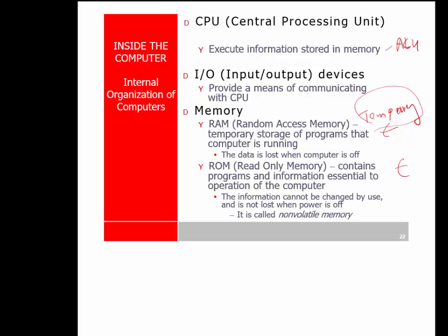The term random access is an incorrect term, in my opinion. Random access means that I can access it directly by just applying the address on the address bus, and we'll talk about that, and reading that memory location. You can do the same thing with ROM.